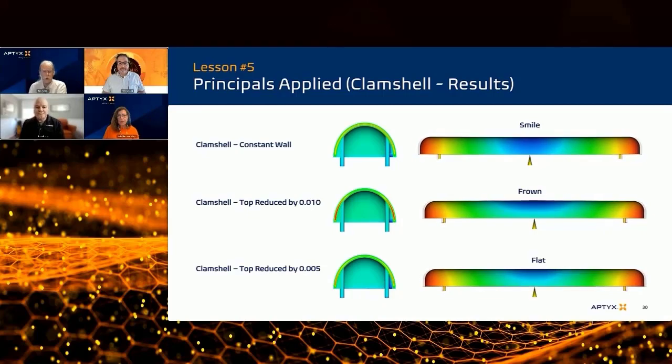Oh, that's a great question. Brian, I think both can chime in on this one. I have fixed parts with differential mold temperature. The thing is, it's most effective with semi-crystalline resins because they have the highest shrink rate and the most movement. I fixed a part a short time ago, I believe it was Delrin. It had a big disc and a shaft, and it was warping the wrong way. The tool was already built, and this was another group. I had to go in and fix it. We went into Moldflow, modeled all the water lines, and worked on differential temperature to tune it. In that case, we got it flat.